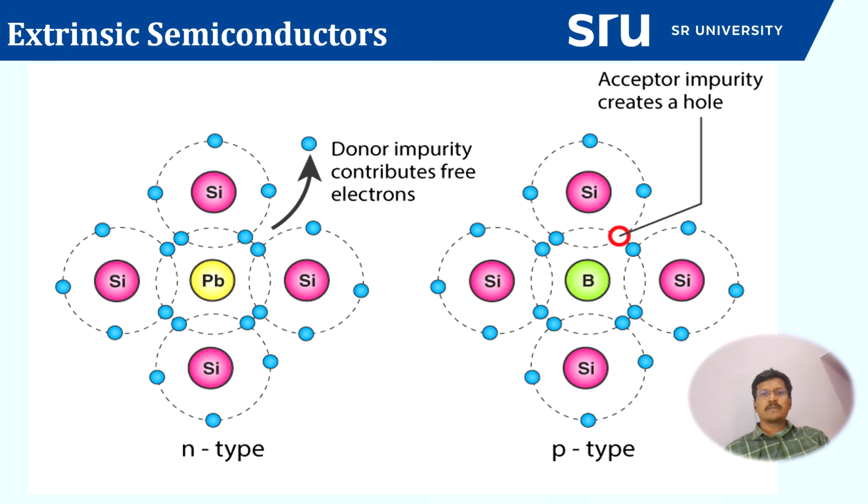Just like one drop of curd will change the complete structure of a full pot of milk, similarly, one doping element can change the entire semiconductor's properties. The purpose of doping is to increase the number of charge carriers and to improve the mobility of charge carriers.